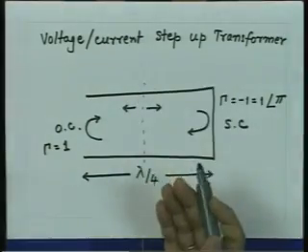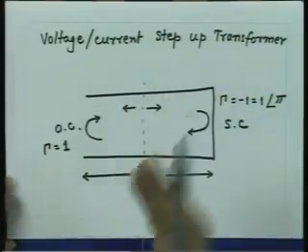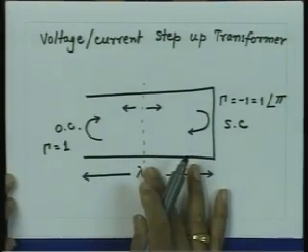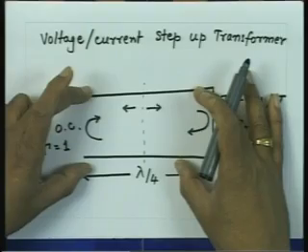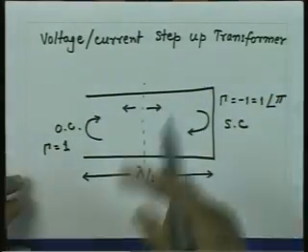One may wonder then how far this growing of the wave will go on. In fact, if there are no losses in the transmission line, this growth of the wave will go up to infinity. So, the voltage will go on growing for infinite amplitudes, because there is no controlling parameter on the transmission line. So, even if a small voltage is induced on a transmission line for some stray coupling or something, and if the section of transmission line is resonant, then the voltage which you see on this transmission line is now much larger compared to the induced volt because of this regenerative feedback.